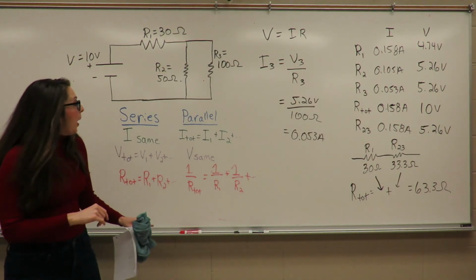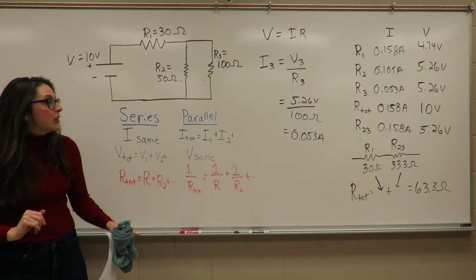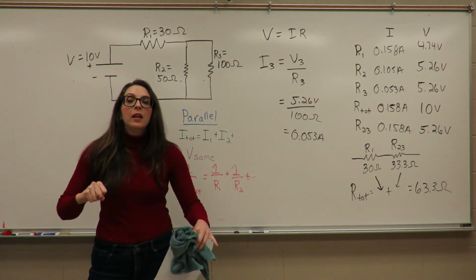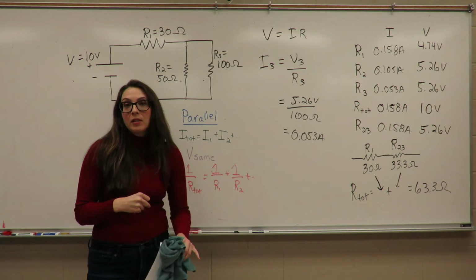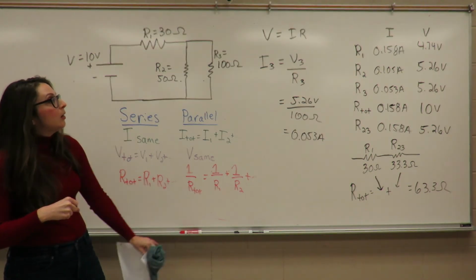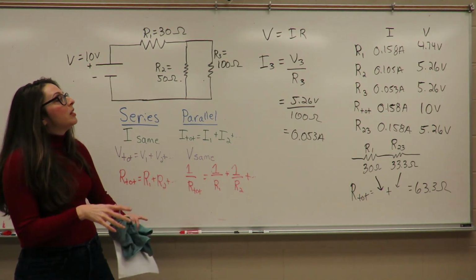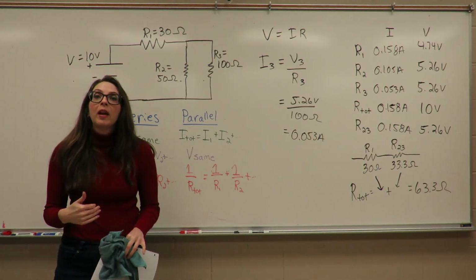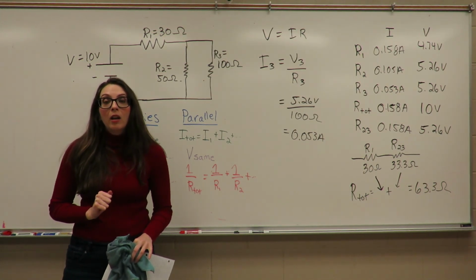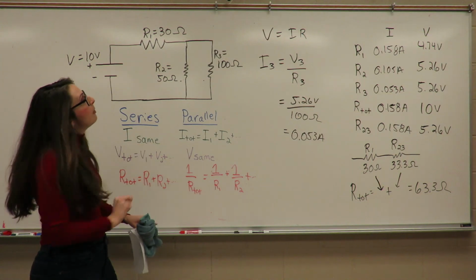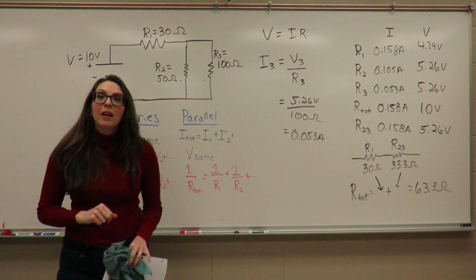Okay, and so starting from my circuit, breaking it down into finding its equivalent resistance in order to find the current running through it, I'm able to then back out from there to find the current and voltage drop across each of my individual resistors in this circuit.